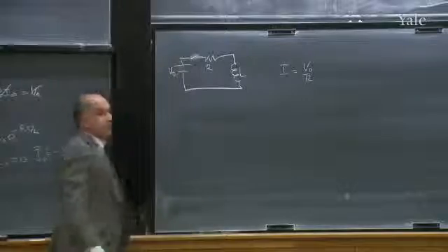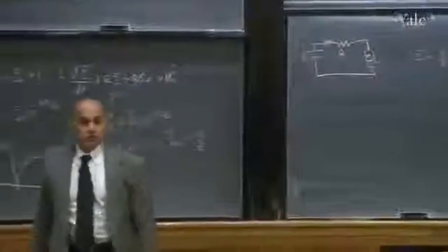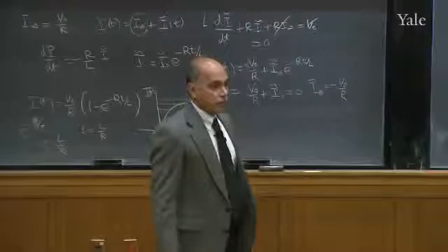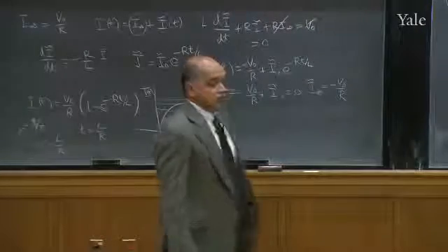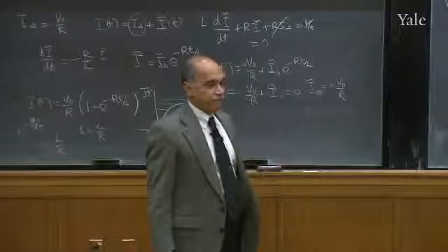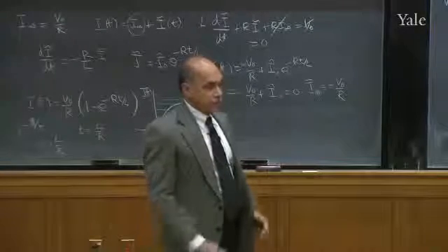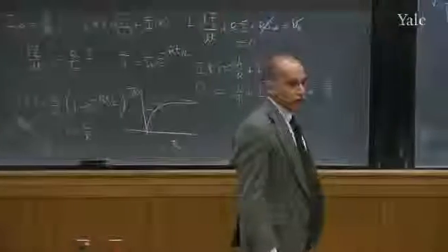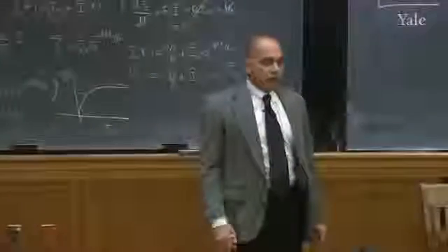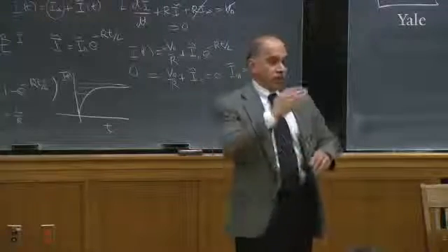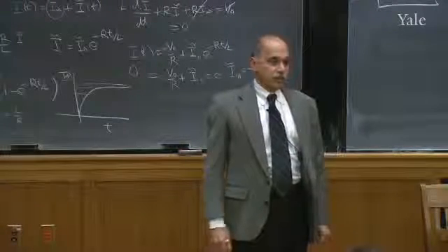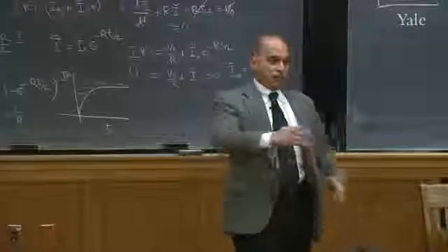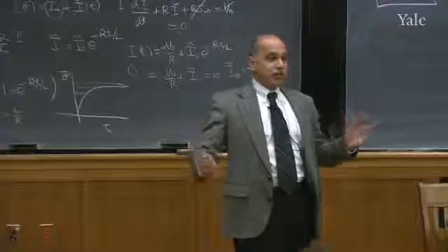So what do you think will happen if you open that switch? Yep, the inductor will resist a change in current. But how can it resist? By inducing a magnetic field. It can do what it wants, but how does it drive a current through the open circuit? From energy stored in the magnetic field. But in what manner will the current flow, given that I've broken the circuit? In the direction. No, but how will it manage to go around? Because it's like removing the bridge, right? How will it go around?